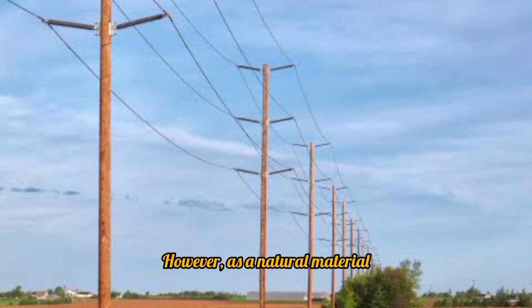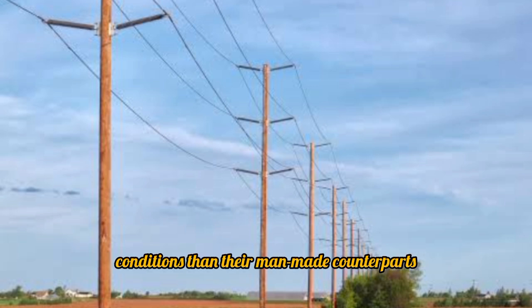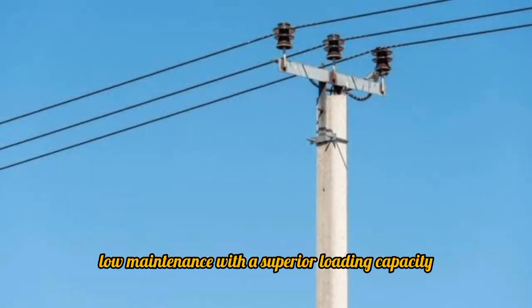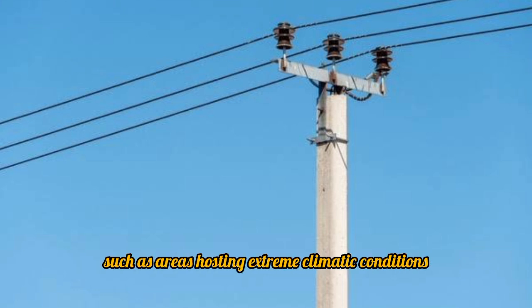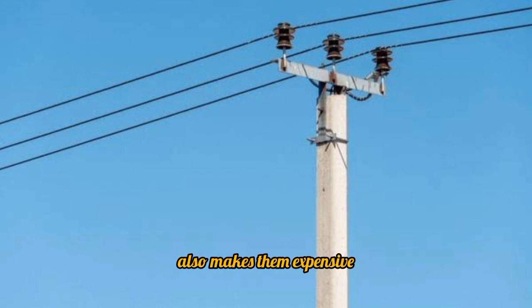However, as a natural material, wooden poles have a shorter lifespan and are considerably more vulnerable to environmental conditions than their man-made counterparts. Concrete, RCC, poles: low maintenance with a superior loading capacity. Concrete poles are a prime choice for supporting structures requiring an extra boost of strength or resilience, such as areas hosting extreme climatic conditions. Unfortunately, their weightier construction also makes them expensive and awkward to transport.